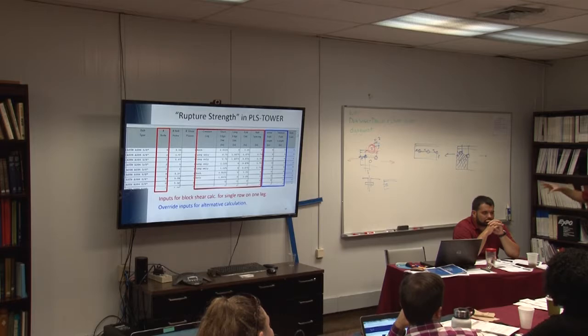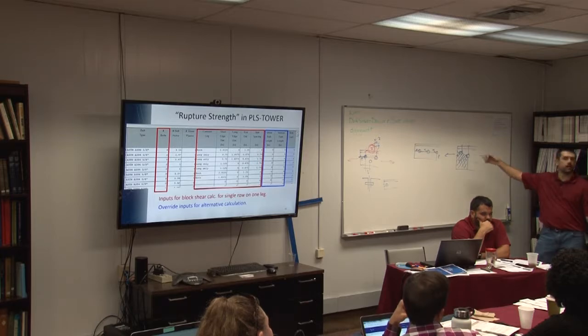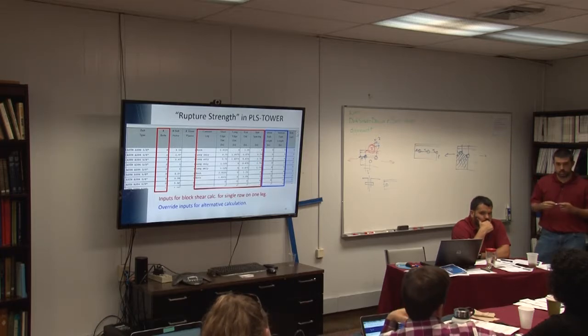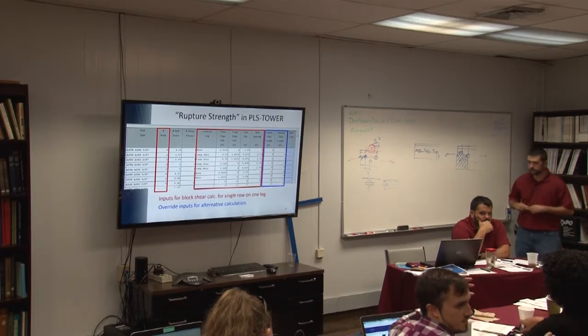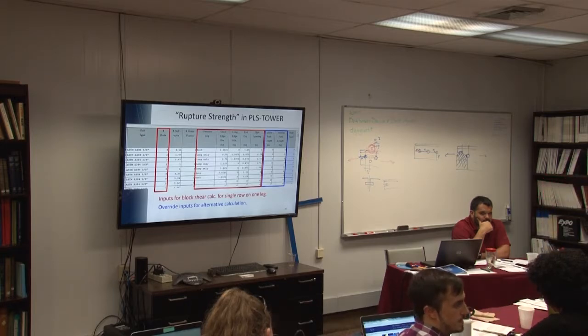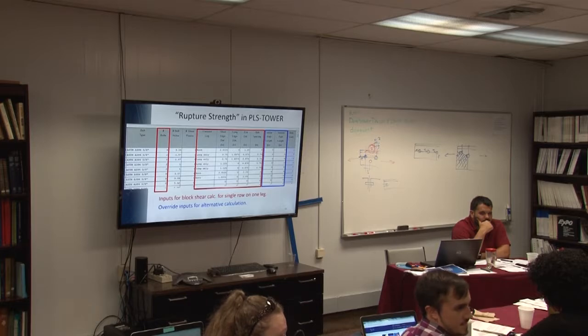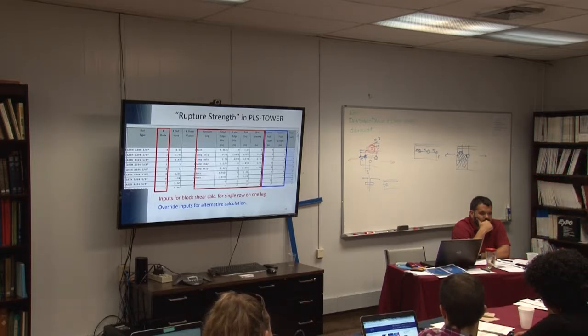What I'll say is that a lot of the stuff we're talking about is mostly for connections that have one or two holes. So for legs with those big lap splices and butt splices, none of this is a problem. I see what Joe's saying, that in a way it looks like bearing would potentially control, but with all the different factors, if you make the holes bigger, then you have a larger bearing surface but a smaller shear surface and tensile surface. So it's all give and take. I think it's also a function of the strength of the material. That's true, absolutely. It's toughness and other things too.